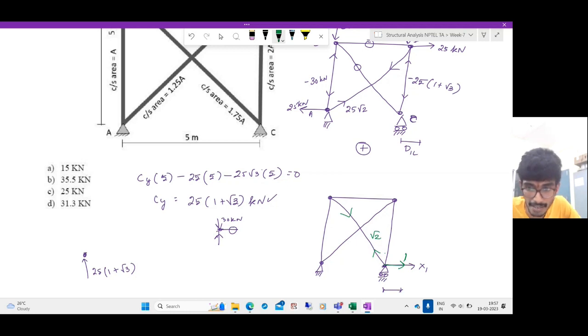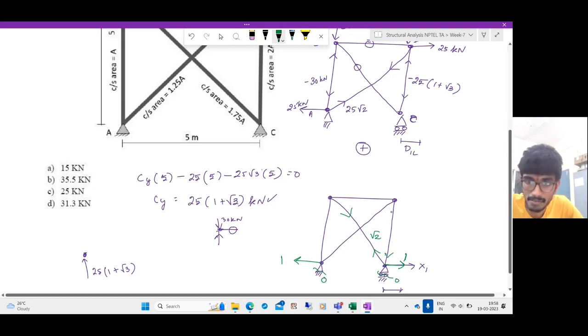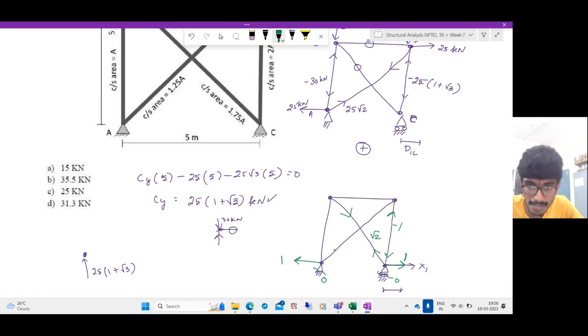There is a reaction here. So the horizontal reaction will be 1. And if you take the total structure, there are no vertical forces, so the vertical reactions are 0. Which means this vertical force will be nothing but compressive -1. Coming to this point, again, due to this, there is a tensile √2. Vertical will be compressive. So again, these two tend to compress this strut.